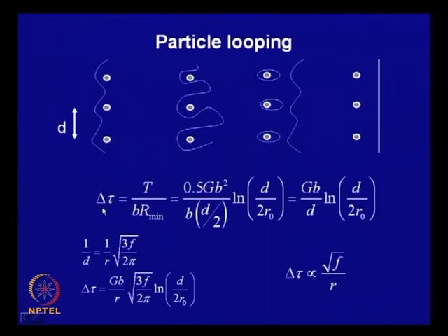And if you remember your earlier lecture, the additional shear stress which you apply, the radius of curvature, is a function of that shear stress that you apply, and this is given by the line tension T over Burgers vector b, and this is the radius of curvature. Now, the minimum radius of curvature it is possible to calculate, and we had done it earlier.